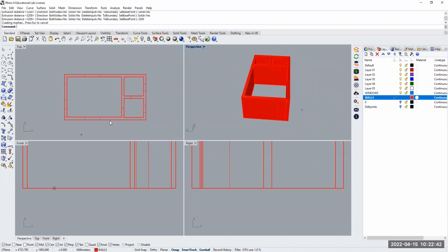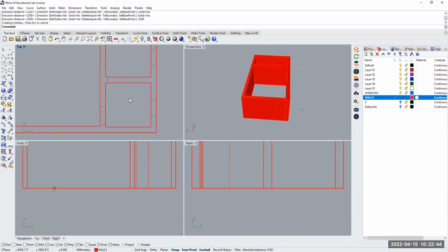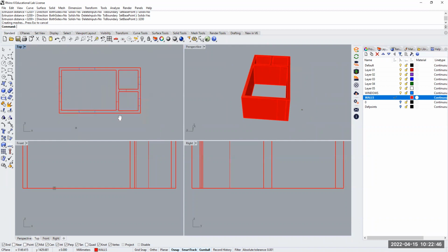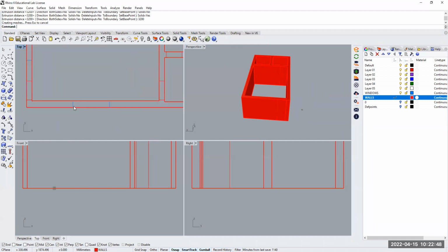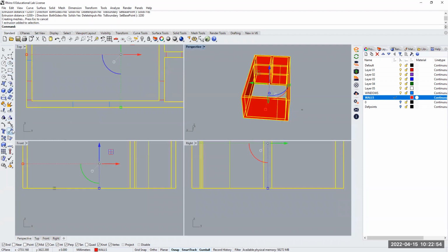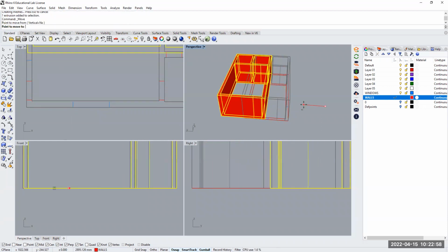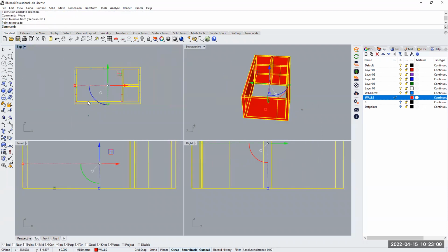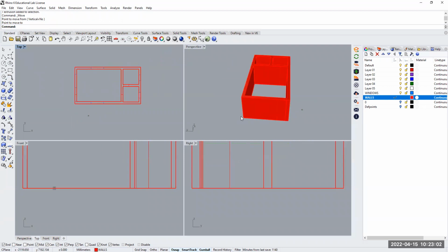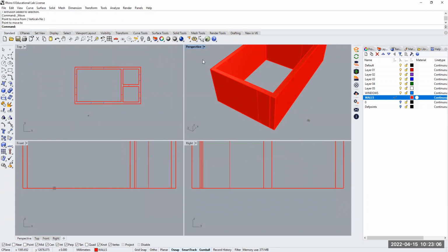The next step is to make the holes. In order to make the holes, I'm going to have to use these rectangles. I can either move my solid object, which I'd rather do, or have these rectangles drawn before I extrude my objects, or you can simply start drawing on it. But in that case, you have to keep an eye on the 3D perspective to make sure that it's snapping to the correct points. Let's do this together.